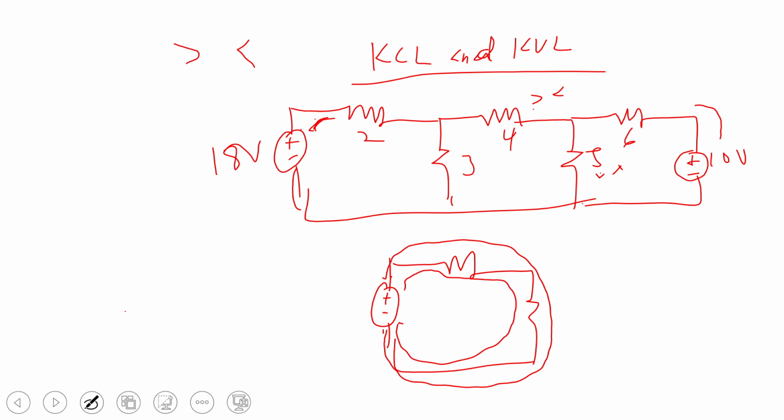So let's say in your house, the amount of current going from one fan to another fan, you may not know whether it's from this one to this or from the other one to the other one, right? So most of the time when you're analyzing circuits with Kirchhoff, you decide the current direction. When you decide that the current direction is this, when you solve the circuit, maybe you get 2 amps. If another person decides the current direction is like this, the person is going to get negative 2 amps. This 2 amps and this negative 2 amps are the same current. The negative is just saying that the direction should have been the other way. That is all.